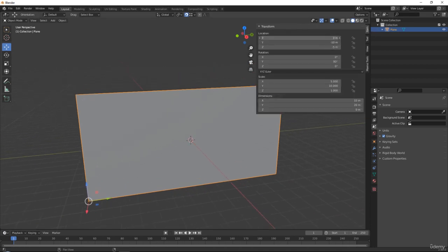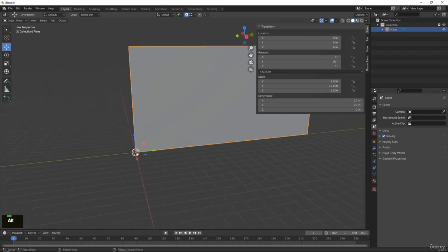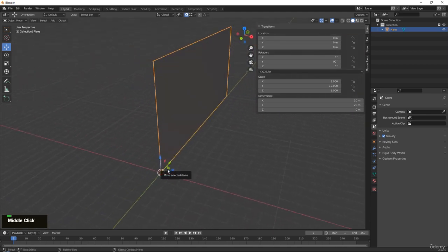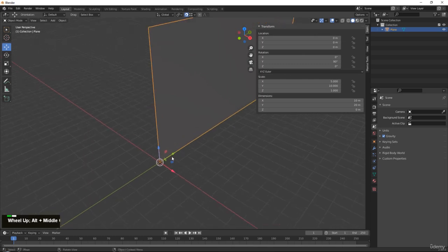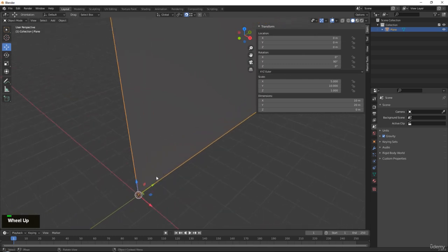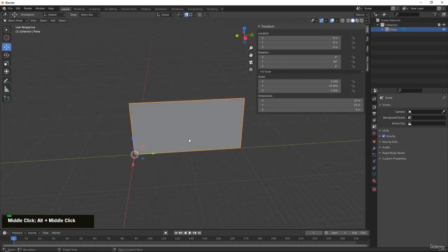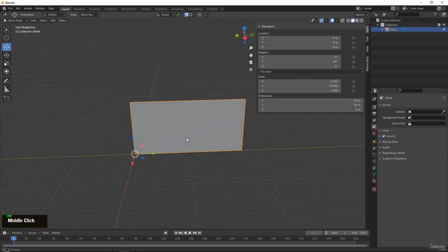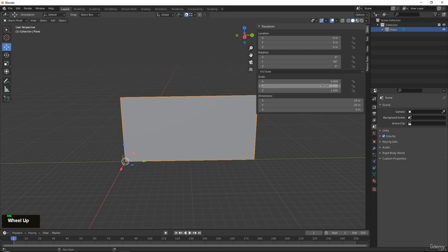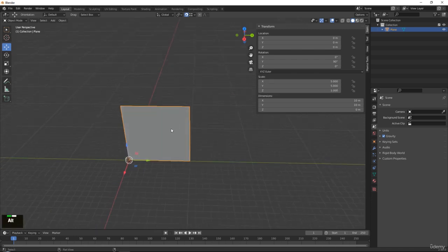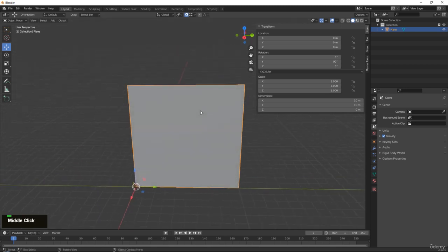At this point, we can go ahead and set the location to 0, 0, 0, which means that this is where our pivot point will be. The way that Unreal reads is Unreal will always place your pivot point on 0, 0, 0. So all your models need to be on, you guessed it, 0, 0, 0. Now that we have this one over here, I will have a look if I need to go. Let's start with like 5 meters. Let's do a simple square to get started with. It's handy to keep it a square because then it is very easy for us to keep it tileable.